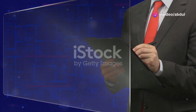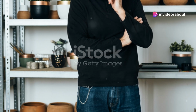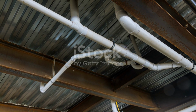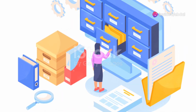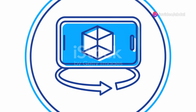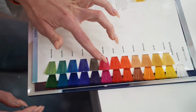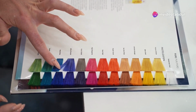Think of layers like transparent sheets you can stack on top of each other. Each layer holds different information, like walls, doors, or, in our case, plumbing. Create layers for your plumbing fixtures, water supply lines, and drainage systems. This keeps your drawing organized and easy to manage. To create a layer, click the Layer Properties button, which looks like a light bulb with a sun over it. Click New Layer and give it a name like Plumbing Fixtures. You can assign different colors and line types to each layer to make them easily distinguishable.